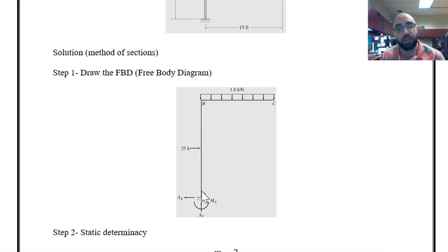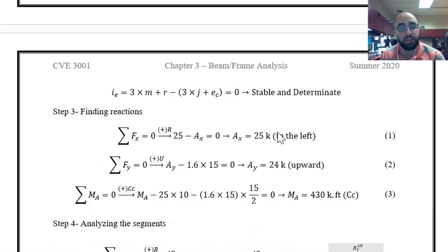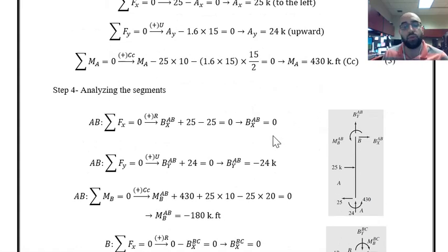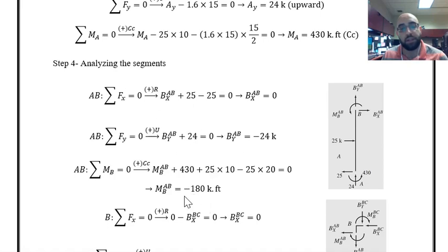We have rigid joints over here, which means that bending moment can be moved and transferred through the members. And then analyze each of these members, or we can say beams. And once you analyze them, make sure you put the reaction of the forces that you have at the end of the beams at the place of the joints and then transfer them to the other member. You can look at the presentation file and the example that I solved at the end of the presentation file, and that procedure is exactly followed over here,